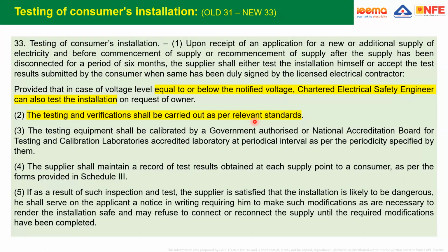Now, for your information, earlier in all safety audits or verification, the first inspection we did was generally the earth pit resistance measurement. And the funny part is the earth pit resistance measurement has been thrown out of the standard. It has been removed from the standard. You don't need to carry out this particular test anymore because earth pit resistance has nothing to do with safety. So I will come back to it later. But anyhow, this is how we should make it.